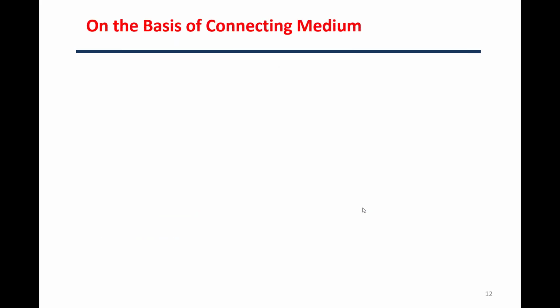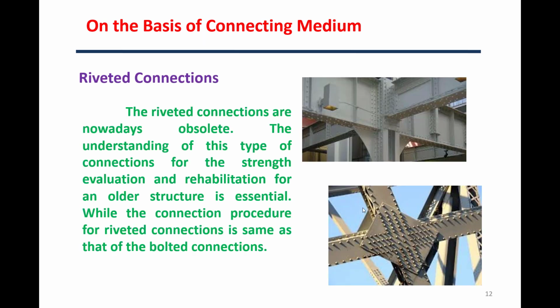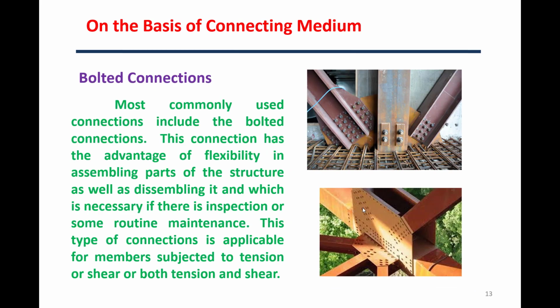On the basis of connecting medium, we have riveted connections. The riveted connections are nowadays obsolete, but understanding of this type of connection for the strength evaluation and rehabilitation of an older structure is essential. The connection procedure for riveted connections is the same as that of bolted connections. Bolted connections are the most commonly used connections.